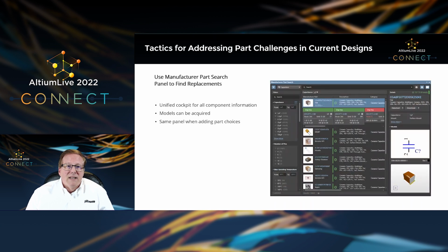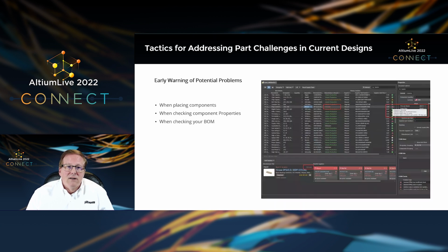And let me just go back here for a second. I just want to mention, as we're talking about checking your BOM, those BOM checks can also be kicked off in the project releaser. So when you're generating your documentation for fabrication and manufacturing, you can actually run those checks, and you might find that you have an issue at that time. And the goal of all of these early warning systems is to detect issues before it gets to the manufacturer, or as early as possible.